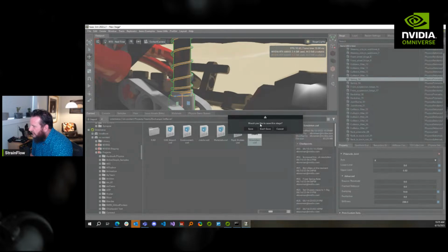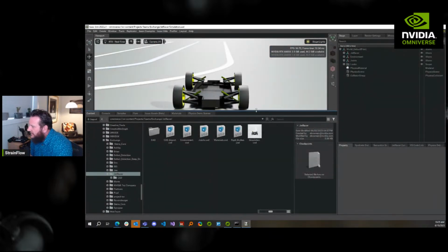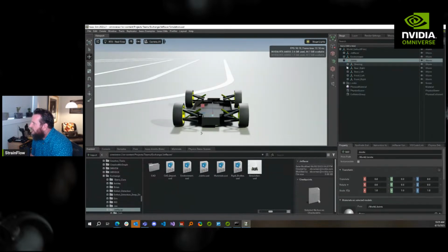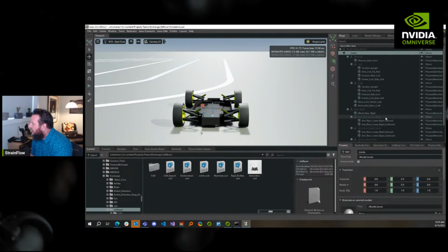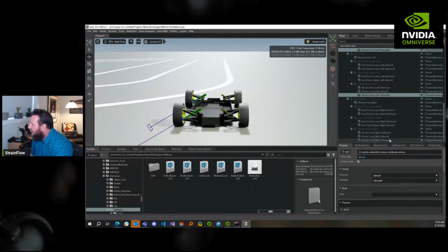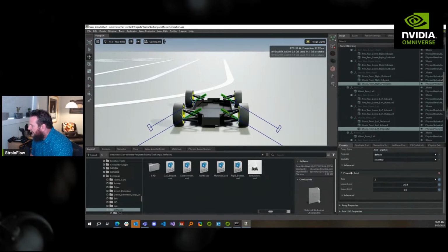So it's maybe 5%. Would you like to save the stage? Don't save. We could try that. Maybe let's tweak the damping first and then go do the convex decomposition after that. Let's see. Joints. Let's grab those three. Oh, there's 4. There we go. And let's go to those limits first. There we go. I just put a tiny limit on it.